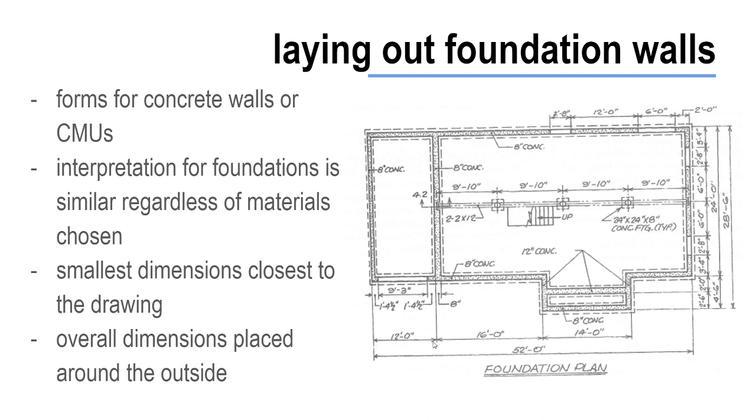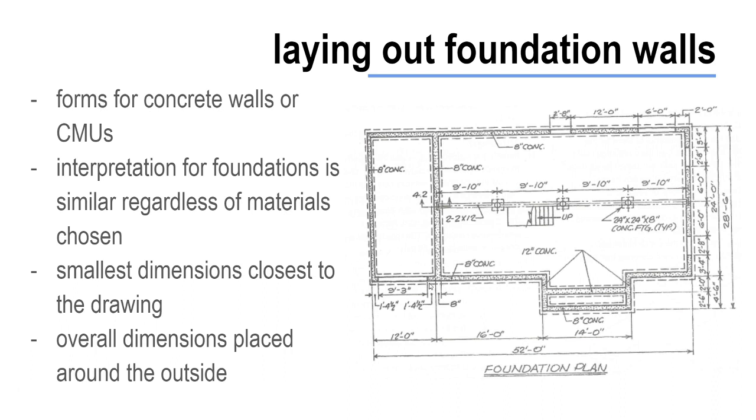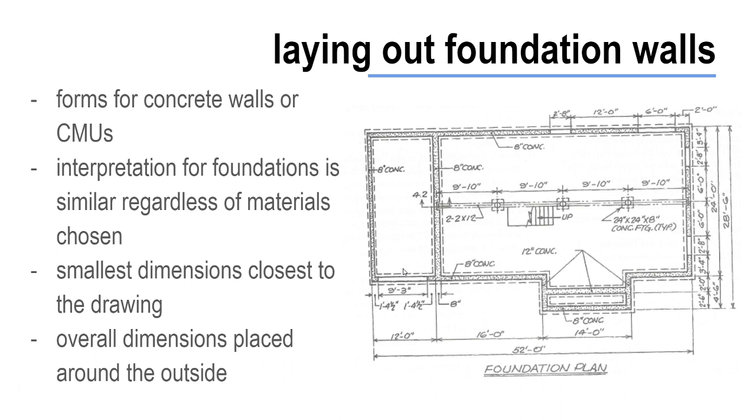Because this is not construction based on wood framing or stick framing yet, and is still just using either bricks or concrete, everything is measured to edges, including openings. If this was stick framing for this opening, then I would be measuring to the center. But because it's being made out of concrete, we're measuring to the edges of openings.